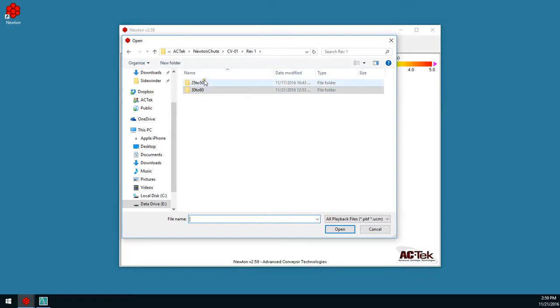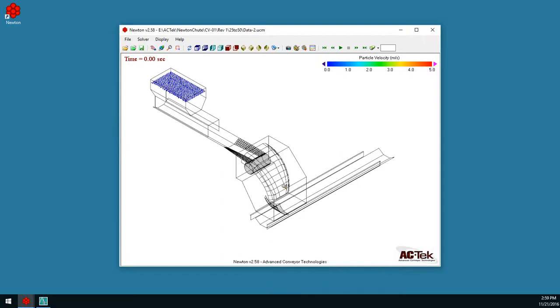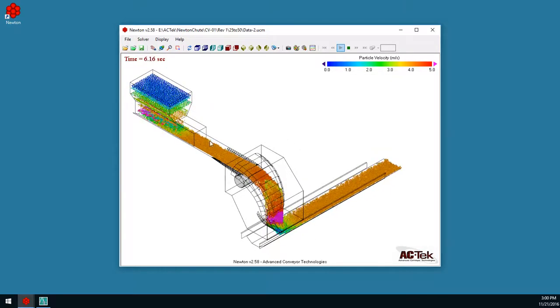As a reference, I ran a few different cases. I ran the 25 to 50 particle set on one of our more powerful PCs, which happens to be a dual 8-core, so there are 16 cores on that. This had almost 650,000 spheres, 240,000 clusters, and it took just over 4 hours, 4 hours and 10 minutes, to run this full simulation. So still very, very quick. And you can see this flow looks very representative. We're still only at 7 seconds here.